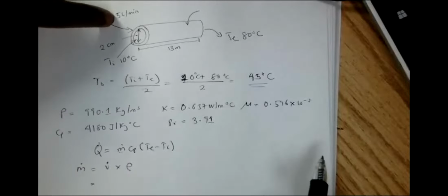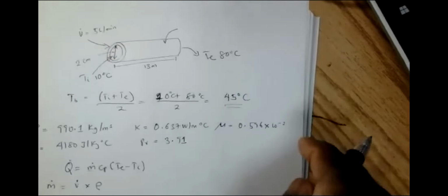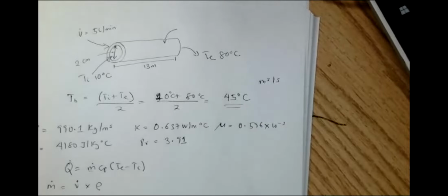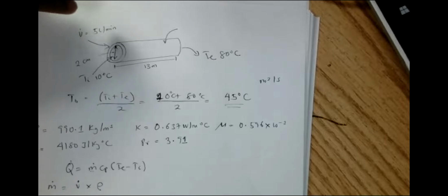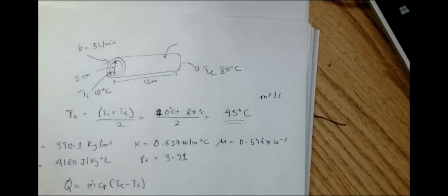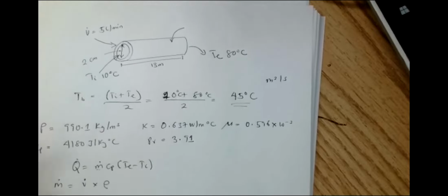So to convert this, you just divide the value by 1,000 to get the equivalent value in meter cube, and then divide by 60 to get seconds. So the standard value should be meter cube per second. So we're going to divide 5 by 1,000 and then divide by 60. So that is 0.005 meter cube divided by 60 seconds. That is our standard value.